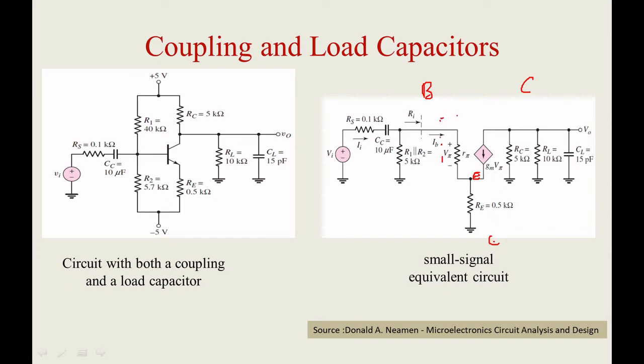So this is the transistor part. The transistor part is over. Now below the emitter you have an RE resistor, so that RE resistor is given. Emitter current is nothing but the sum of your base current and collector current. Here I am taking it as Ri. So Ri means the resistance in this part, that is R pi plus (1 plus beta) times RE. That is the reflection rule, which we studied in the last slides, right?